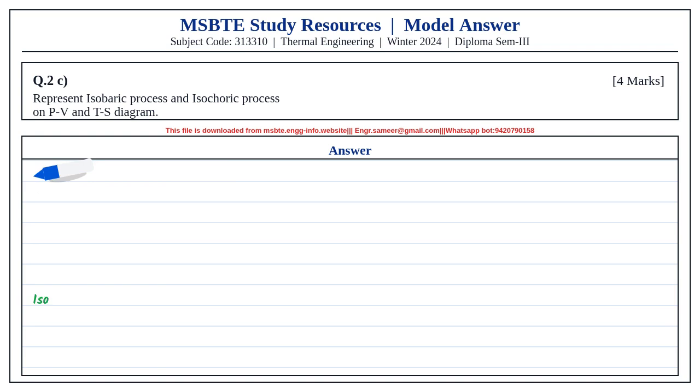In reaction turbine, steam expands partly in nozzle and further expansion takes place in rotor blade passage. Relative velocity remains same in impulse turbine, while it increases in reaction turbine.